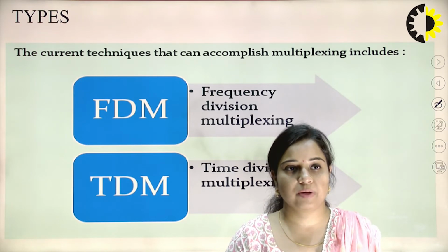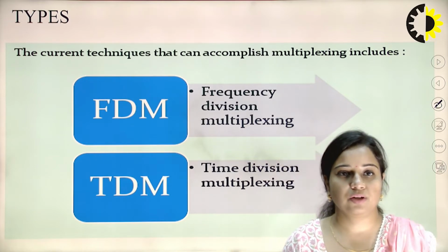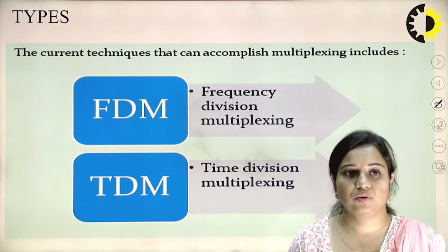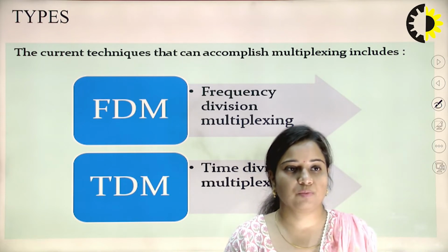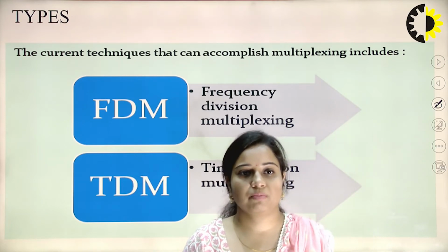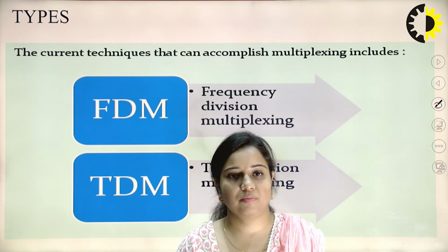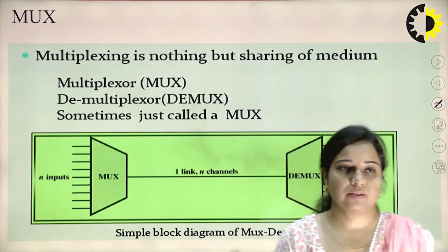So, guard band is basically inserted between two different users to reduce the intersymbol interference problem or any kind of problem that will occur due to the spreading of the pulse when it will travel over the channel. So, that is the case of frequency division multiplexing in the simplest manner. In case of time division multiplexing, whatever time is allocated for the whole transmission of information, it should be equally divided among different users. So, that is the case of time division multiplexing.